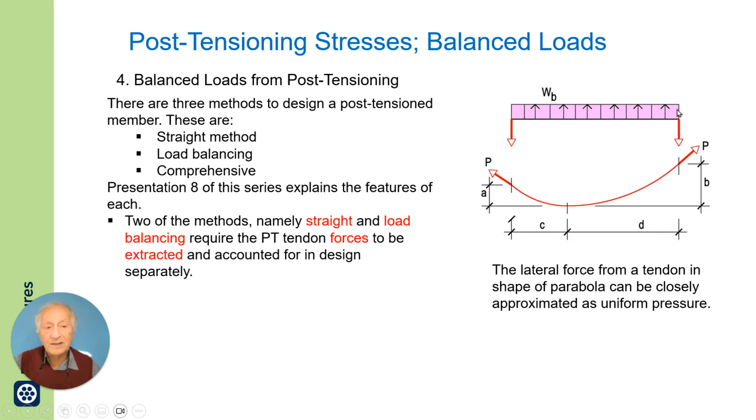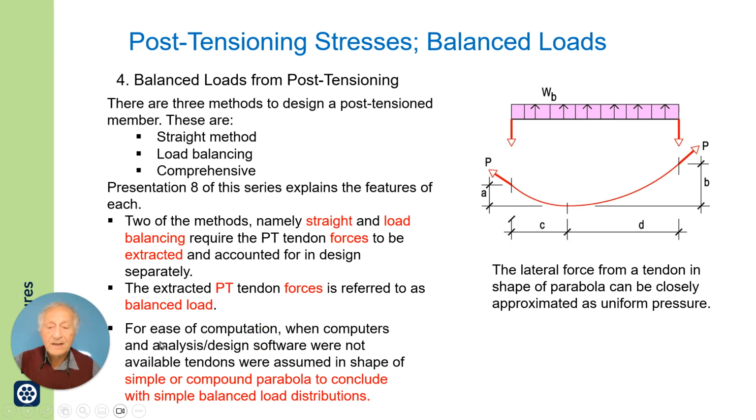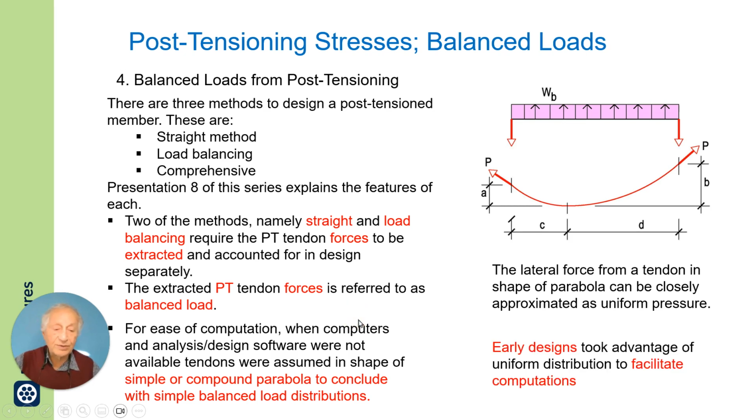That makes the calculation easier than otherwise. The extracted PT tendon force is referred to as balance load. For ease of computation, when computers and analysis design software were not available, tendons were assumed in the shape of simple or compound parabola to arrive at simple balance load distributions.